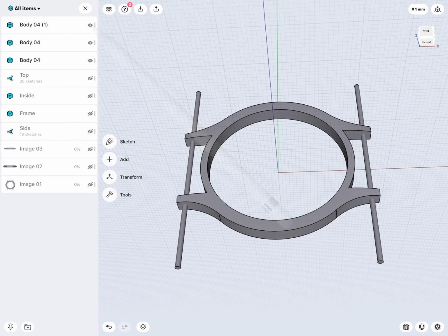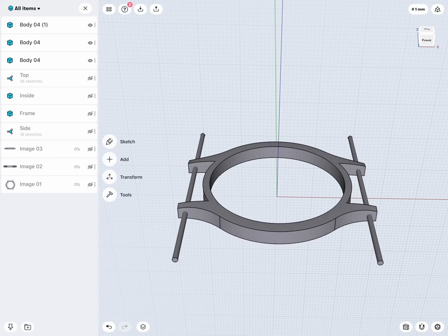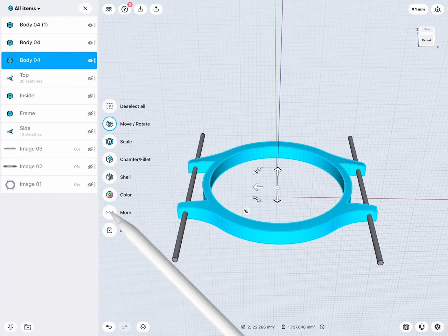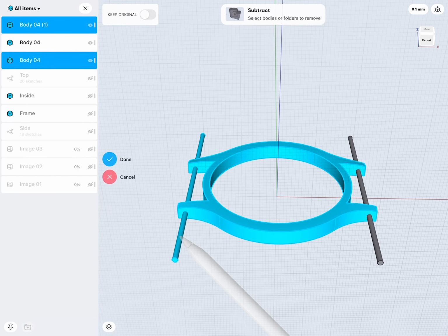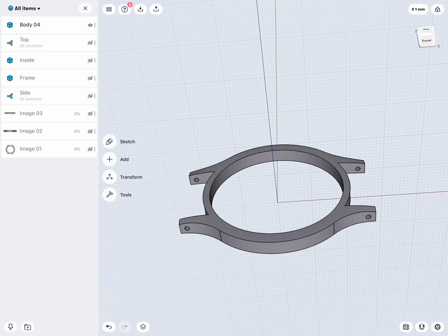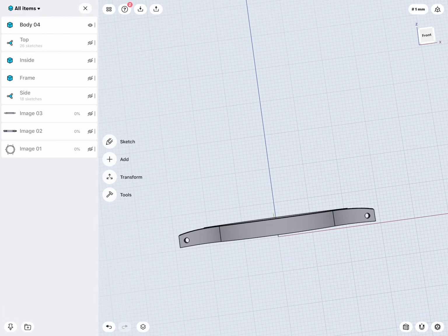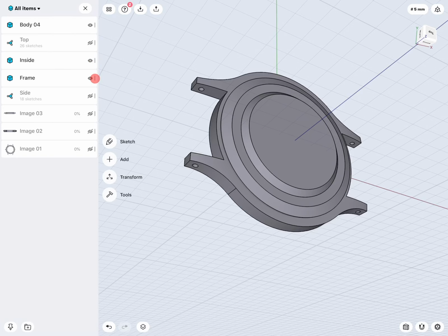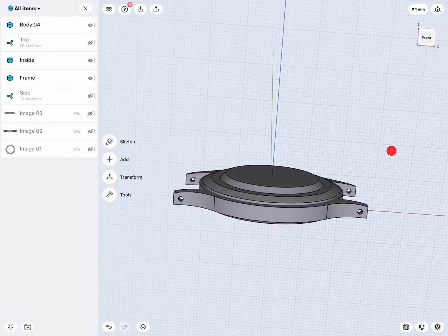And by keeping the sketches this simple, you just make your life a lot easier. Now this one I would like to be having the volume of these two horns removed. Very good. And also because I set everything up and work with the grid, like even with the mirroring of these two cylinders, as you can see, I work very loosely with the dimensions in sketches because I do a lot with the grid by moving it accordingly. It's a very powerful tool. So this is all now set.